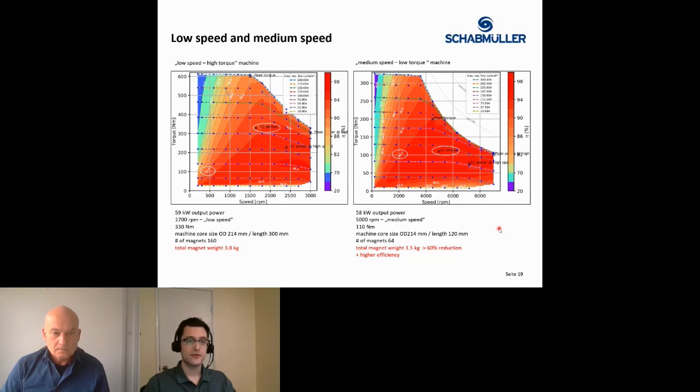Here's the first one. What about induction machines with wound rotors? Is this a valid alternative? We have seen recently the solution on a BMW application. So wound rotor, and that was then not an induction machine, but a separately excited machine, I guess. Yes, this can be an option. So you supersede your permanent magnet field in the rotor with an electrically excited field in the rotor.